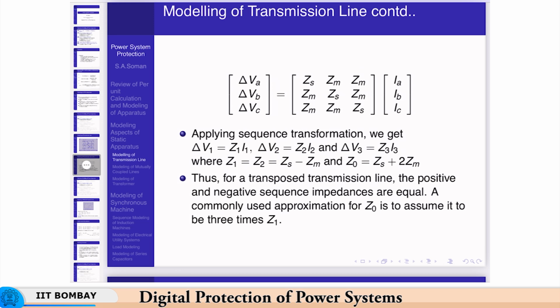So, even if there is some ground resistance or ground impedance present, since the current is 0, the voltage drop will be 0. So, it does not matter what the ground resistance or impedance is. Here, in case of zero sequence currents, some part of the current will return through the ground, some part will be returning through the earth wire, etc.